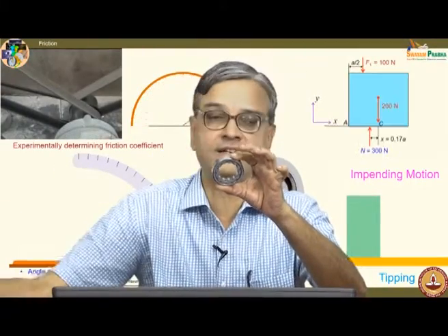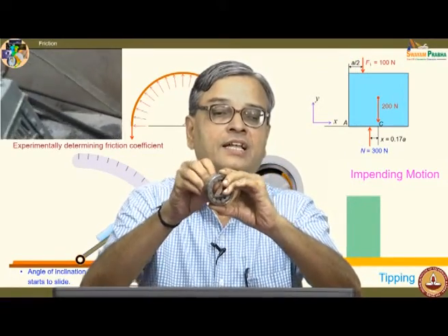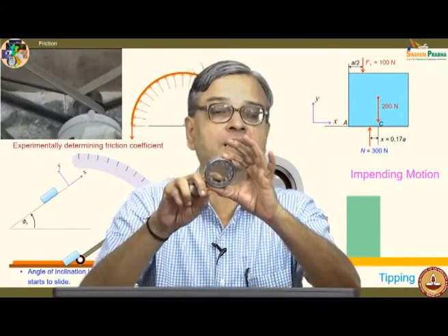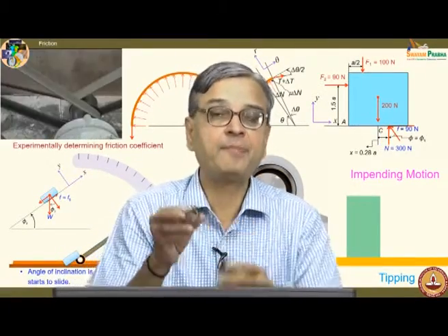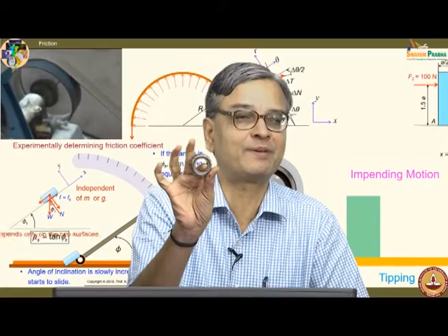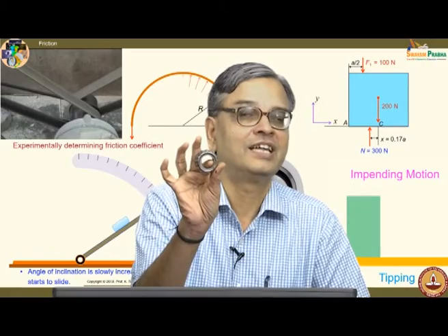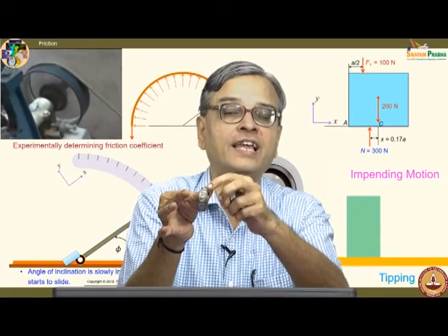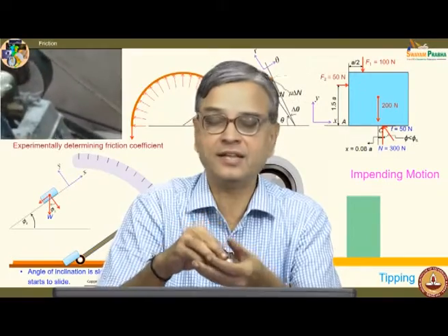Okay, the inner race is taken out. There is an inner race and there is an outer race. So, this will take more radial load than a simple spherical ball, and you also have tapered ball bearings. You look at the kind of complexity engineering has developed into. Once they have recognized that rolling has the least friction, they have devised various gadgets, and in this what you find is it can take both axial and normal load. The tapered ball bearings are there.